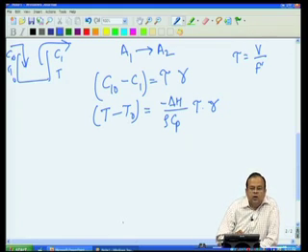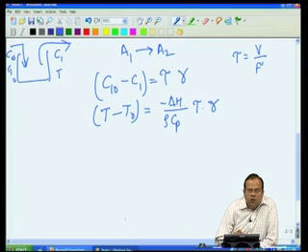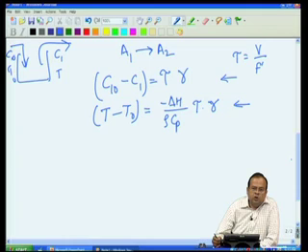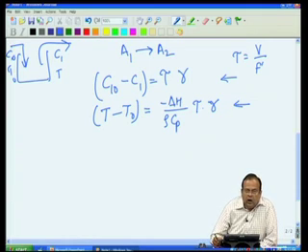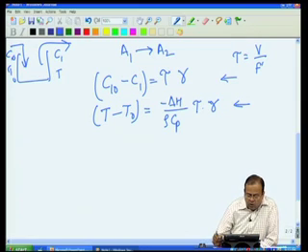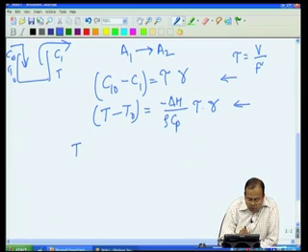We have written the enthalpy of the mixture in terms of its density and specific heat of the mixture rather than considering individual components, and then if you rearrange we will get this kind of term. Now, this is our energy balance, this is our mass balance, and if we assume all properties such as Cp, rho, R are constant, we get this particular balance, and let us try to simplify this further.